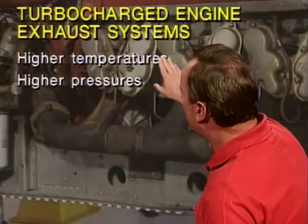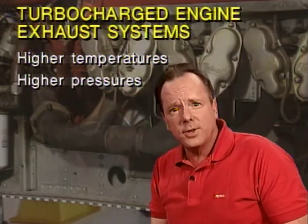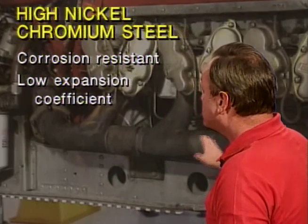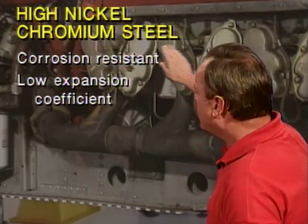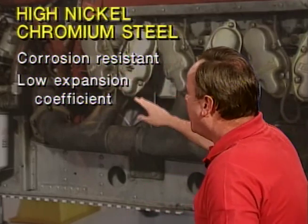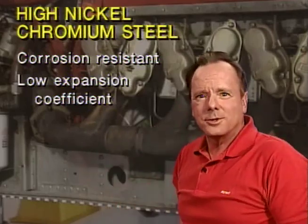So the thing you need to know is turbocharged engine exhaust systems operate at higher temperatures and higher pressures. Because of these high temperatures, you need to have a little fancier materials to build the exhaust system out of. So when you have these high pressures and temperatures, like in turbocharged engines, very often they use high nickel chromium steel. In addition to being able to take the high temperatures, this high nickel chromium steel is corrosion resistant and has low expansion coefficient. It doesn't expand and contract as much as normal exhaust systems.